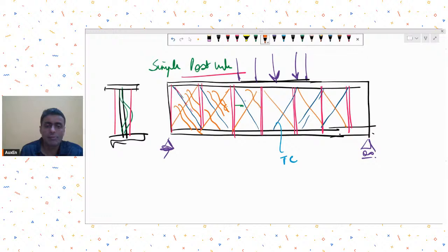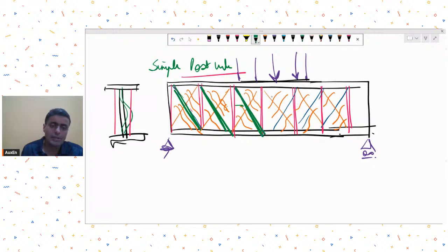But still, even if we were to load this plate girder beyond this, even beyond this state, we are now calling it the post buckling state. My web has buckled, the compression chord of the web has buckled, but still if I increase the load, what do I see? That my web is still able to take loads. Why? Because now these are acting as my tension chords. So imagine it has become a truss-like system where these are my tension chords.